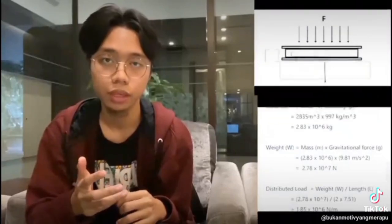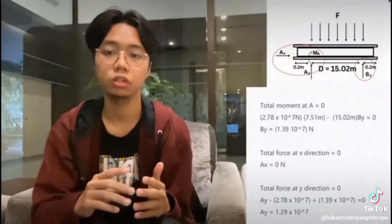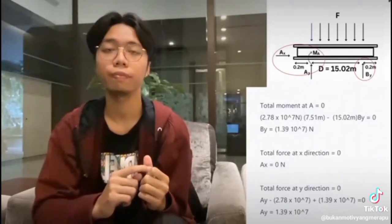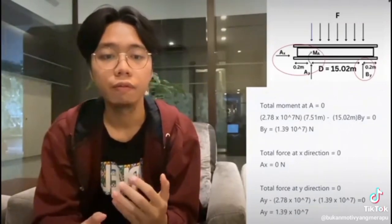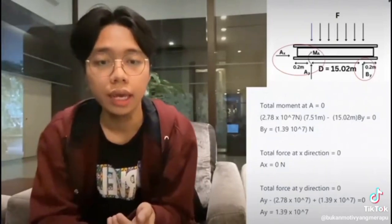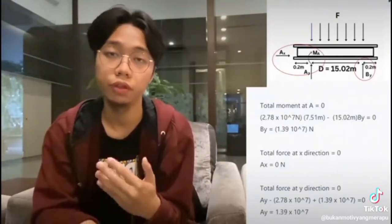And then for the forces at the supporting beam, I only use three equations of equilibrium, which are total moment at A equal to 0, total force in the X direction equal to 0, and total force in the Y direction equal to 0. So from this calculation, we found that both forces at A and B have equal values and an increase by 30% from the original value of the forces.